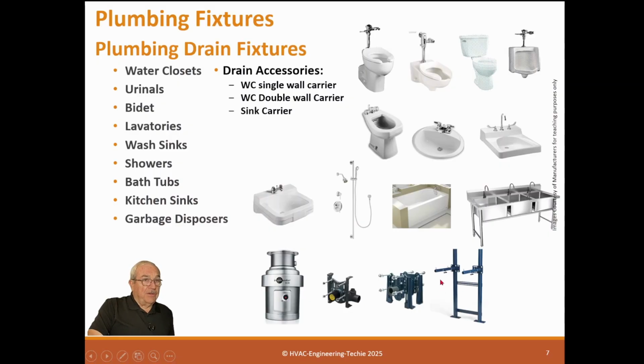This has to be a carrier for a sink. If you have a sink like this or like this in a commercial setting, they will use a carrier like this, which is built into the wall, and these arms come out and actually carry the weight of the fixture. This is fixture trap installation.